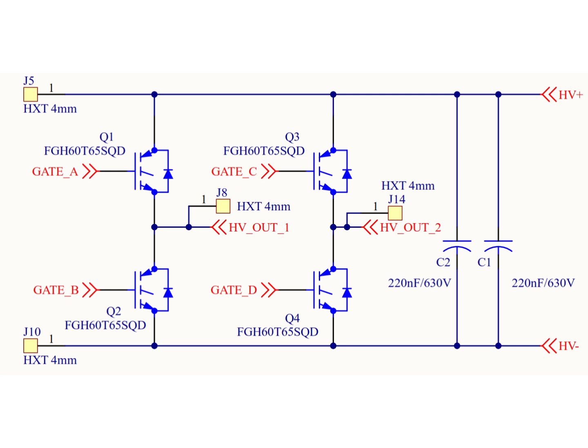Efficiency is another major concern at 3.3 kilowatts and 20 kHz switching frequency, so let us briefly look at losses. Starting with conduction losses, the typical VCE(SAT) of this device is about 1.6 volts at 60 amps, increasing slightly with temperature. At our actual operating current of 10 to 15 amps, the saturation voltage is lower, typically in the 1.3 to 1.5 volt range.